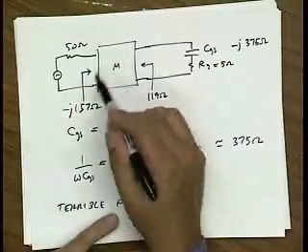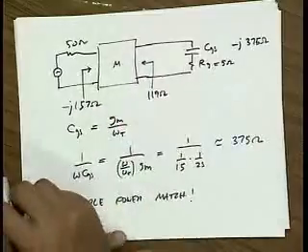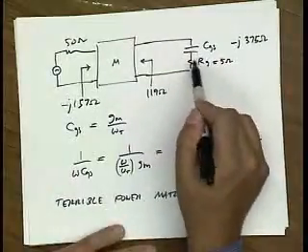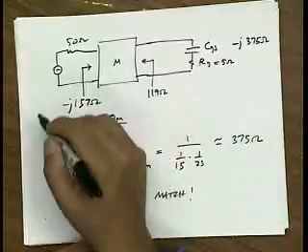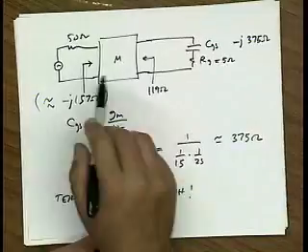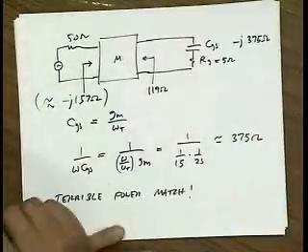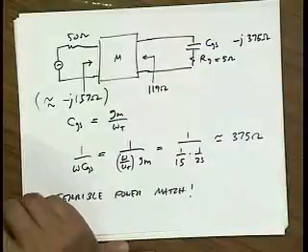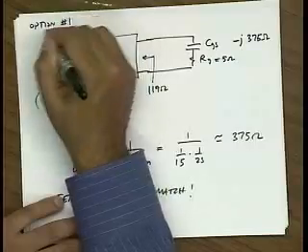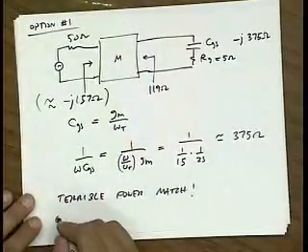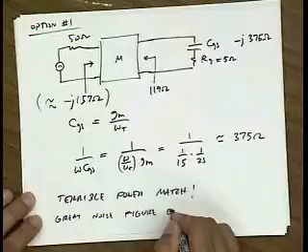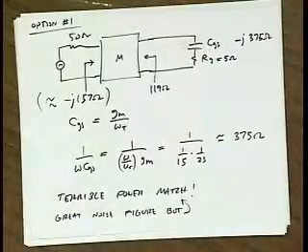Of course, I'm assuming this is an ideal matching network that just transforms anything you give it. In reality, we know that the matching networks we design are used to match real impedances, right? So this is really an imaginary kind of calculation. But the point is that you're not seeing a power match, and so your filter is going to have additional insertion loss, and you're going to lose a lot of signal because of this. So let's call this option 1. We get a great noise figure, but a terrible power match.